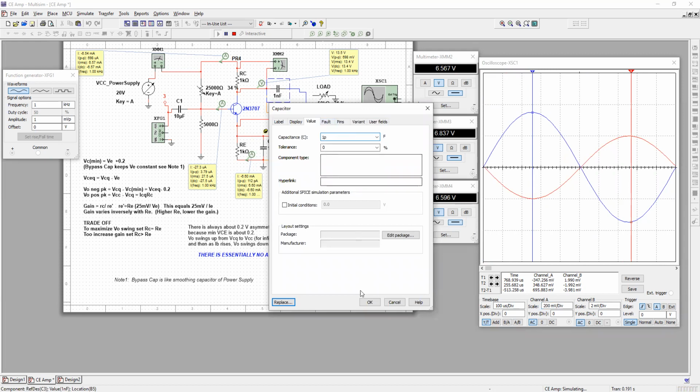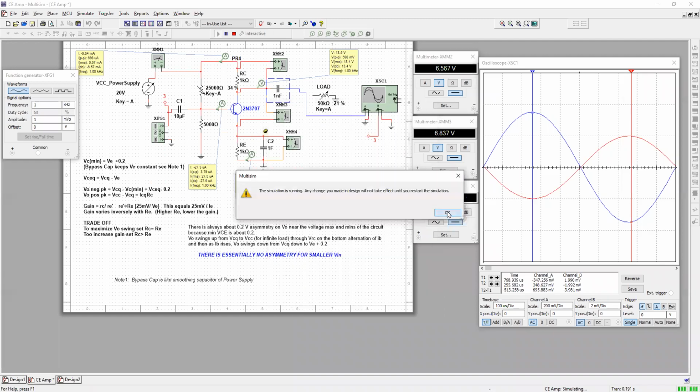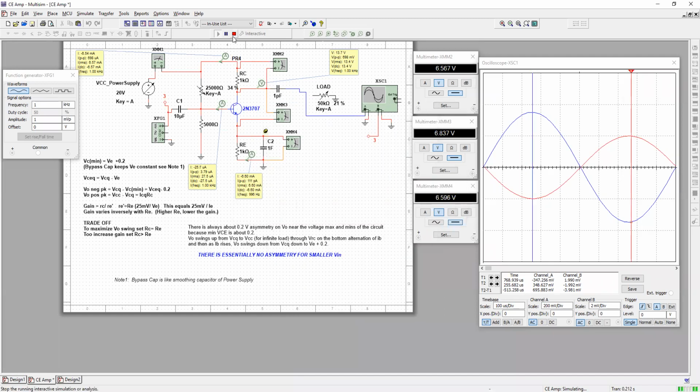You have to realize that when you're pushing the limits of things, you have to think of other things that might be also at the limit, like our infinite resistance. So it could hide the effect of certain other components. Let's see if it's hiding the effect of this capacitor. Okay, so as you can see, I could take this capacitor down as low as I want, and it's not going to change much because I have no load attached.